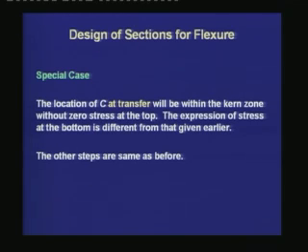Now, when the E is determined based on the cover requirements, then the location of C at transfer will be within the kern zone. Since we have not been able to push E as much as based on the analytical expression, C will also not be at the bottom kern point, but it will be within the kern zone without zero stress at the top.